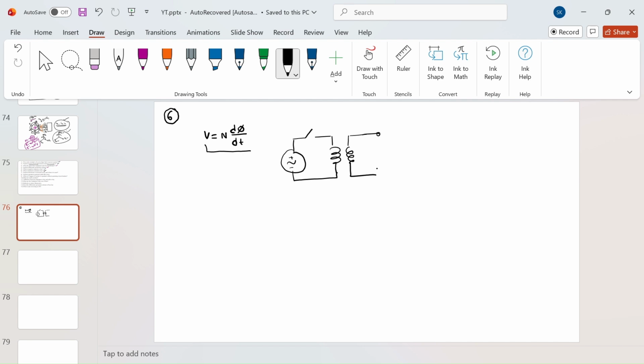If you switch it on, you can end up with a huge no load current, or huge magnetizing current, and that magnetizing or exciting current can be 5 to 6 times the full load current. This high magnitude current can be a trigger point for the overcurrent relay, which I'll also discuss, but let me first explain what happens.